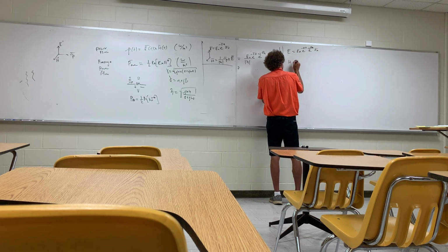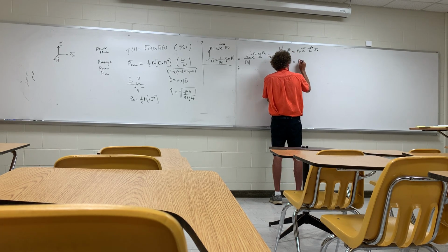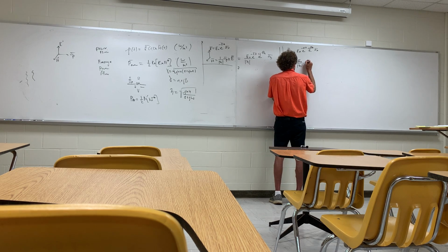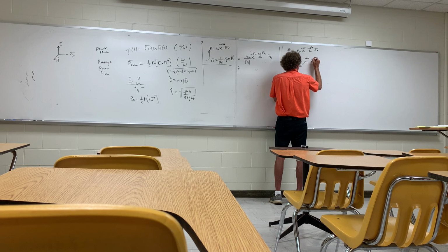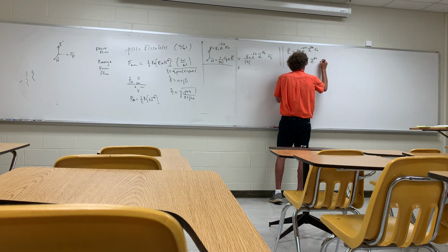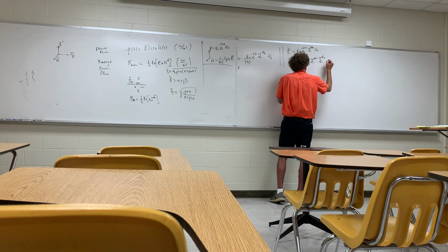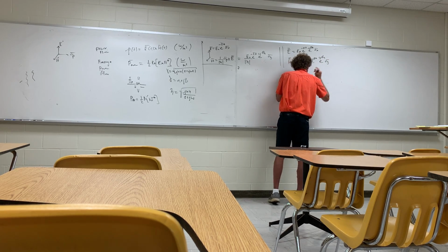And the H field, these are both phasors, would be E naught over the magnitude of eta, e to the minus alpha z, e to the minus j beta z, but it will also have that e to the minus j angle associated with eta here, in the a_y direction.